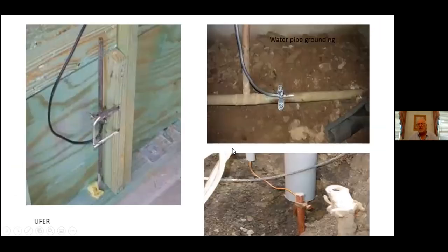Most important, of course, what we talked about was the grounding. Very common in the old days, the 50s, was when we had galvanized steel or copper coming in from the street. The main ground wire from the panel would go to the water pipe, so we would be grounded there. A lot of grounding poles on the exterior were driven 6 feet into the ground, and then the wire could be attached there. But what's most common today when we're building on a slab or with a poured concrete foundation is the rebar that goes all the way through the foundation into the dirt.